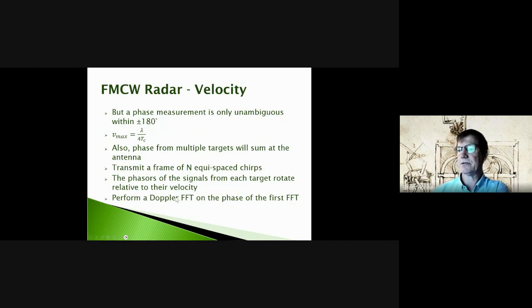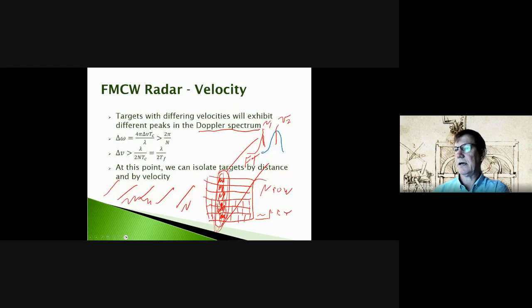So now this is our second FFT, and I've got this horribly crude diagram here where we're sending out pulses and gathering data in time, doing an FFT that gives us data in the spectral domain, and we can load up this matrix one after another after we've done n transmissions. So we have n rows of these things.